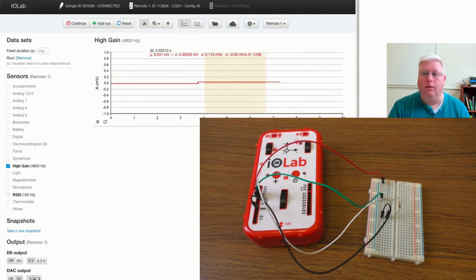When we are applying 0.5 volts, okay? And then you'll just continue going up at 0.5 volt intervals all the way up till you get to 3 volts. And there's a table in your lab report document that you can put in the current. Okay, and then there's a few other things I'm going to have you do there. You're going to make a graph, and then from that graph, you'll be able to determine what's the true resistance of your 10,000 ohm resistor.